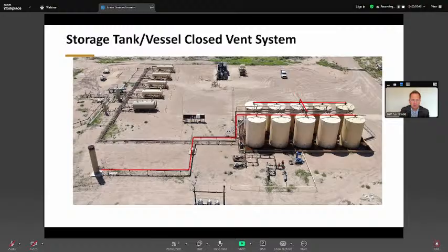And through low pressure flow theory, that makes a big difference. The tank at the end of that vent will have far more back pressure to go than the tank right before it goes to your flare. And so we'll want to pick the furthest tank away so that we are modeling from a conservative basis, unless you know explicitly where fluid's going all the time.